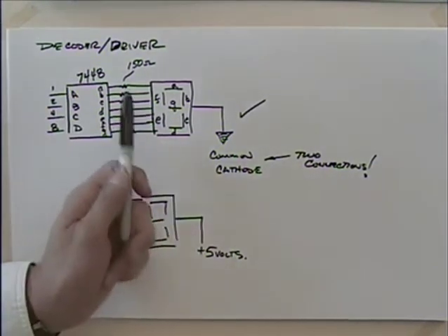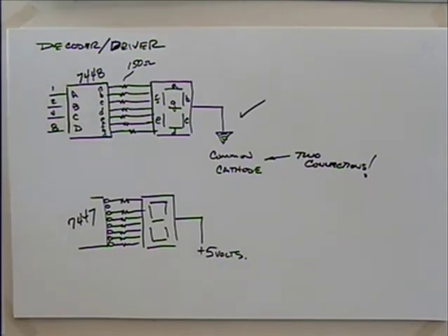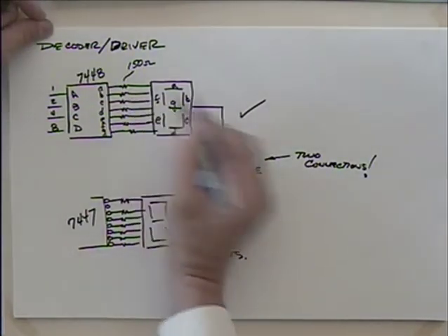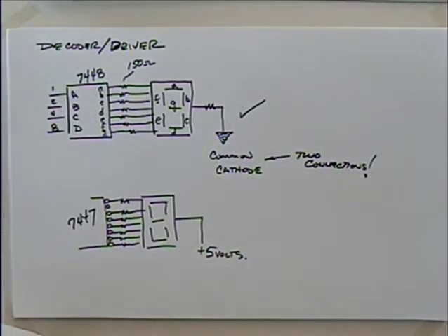A lot of times students don't want to have to go and get 7 resistors, so they'll try and shortcut this process. And I mean, 150 is not exact, somewhere between 100 and 200, you're probably going to be okay. But what they'll do is they'll take these things out and then they'll put a resistor there. I'll say, okay, it's in series. What's the problem with that?